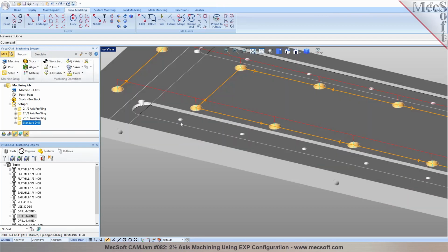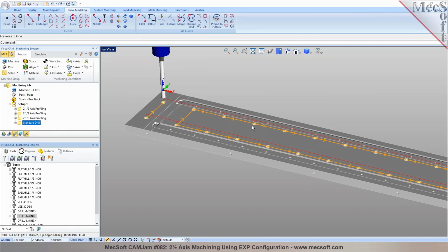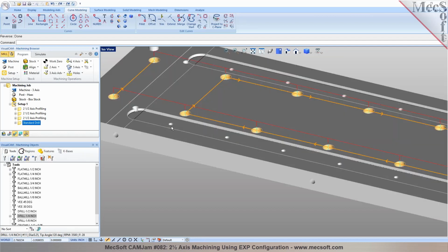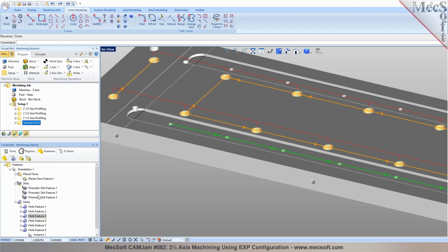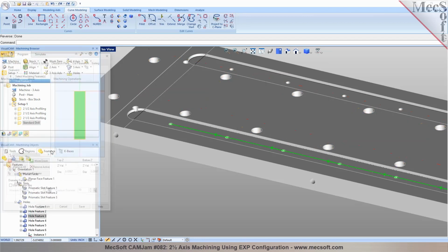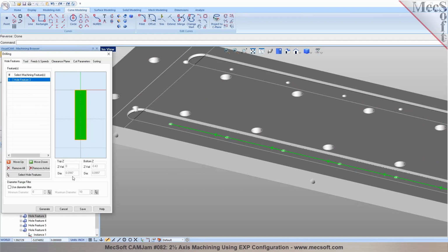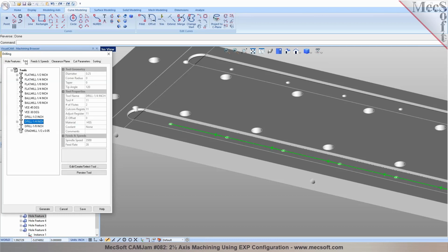The next thing you want to do is tap these holes in here, right? Drill and tap. The holes that are inside of the slots that we cut. Yeah, so you basically want to do it. We have a dimension here. It's a 0.097. So we can go ahead and program. It's a number 4 tap. As far as, do you want to do a drill before you tap, right? Yes. Oh, yeah, we'll drill first.